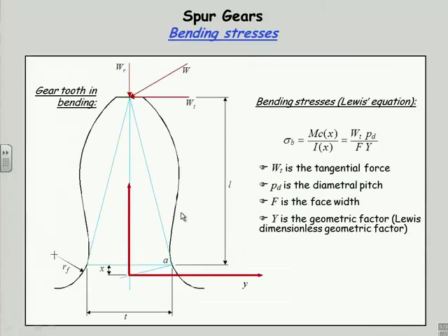or it might be this HPSTC business, the highest point of single-tooth contact, because of the multiple teeth in mesh. Now here's a more realistic looking tooth, although it's a little bit funky, because it looks like I have some interference here. It's getting narrowed down where I'd like it to be. It's just a schematic, and it points out that the narrowest portion here is the weak link. That's where I would expect it to break.